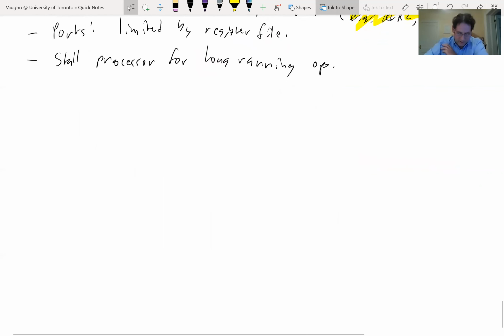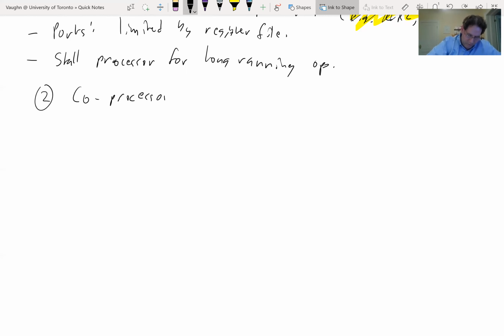So to Camilo's point, that is a good idea. Let's give our coprocessor access to more memory, allow it to operate more independently, and then we can get a bigger benefit from it, and we can get more parallelism. But what people have done is they haven't done that as custom instructions because it's hard to integrate something like that as a unique instruction. And instead what they've done is they integrate those typically as coprocessors. Okay, so that's the other way that you can augment processors.